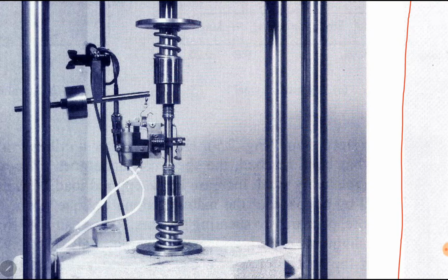Okay, if we look at the steel 1020 HR material here, the curve gets flat after a certain value of stress, like this one. So whatever the number of loading cycles are, this steel material will not fail below this stress. For example, this curve is getting flat at 30 KSI.